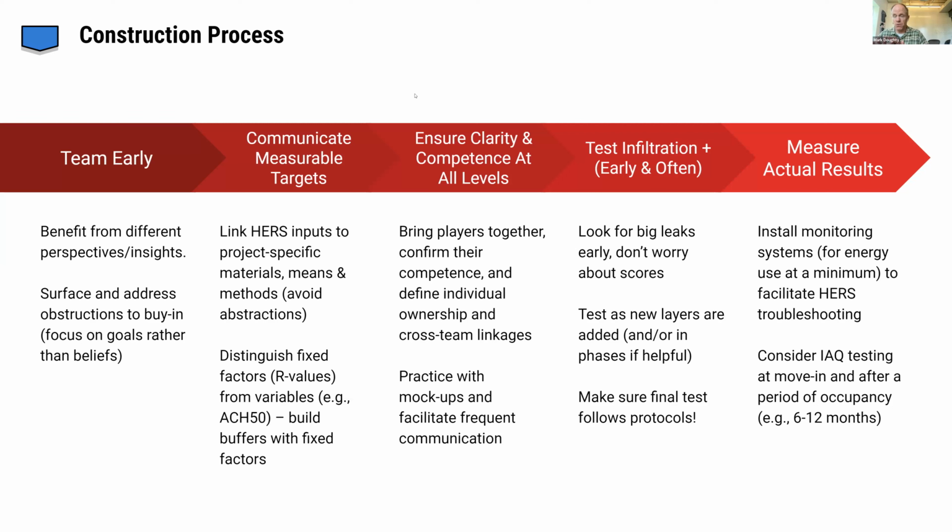Because you might have all these people going around. You have an electrician apprentice who needs to move an outlet, digs out a bunch of insulation, cuts a hole in the air barrier, and doesn't understand how that hole is linked to the overall goal. And the next thing you know, you miss it, you get to that final blower door test and you don't understand where that big air leakage is coming from. And it could just be a few of these holes that have been cut by someone lower on the team. So it's making sure everybody's clear on the goals, competent, and that it happens at all levels of the project.